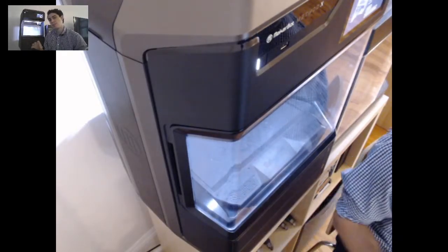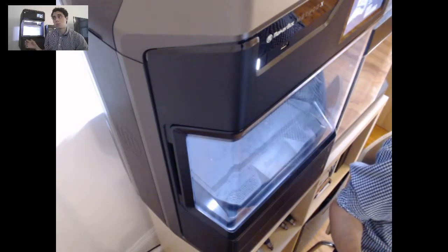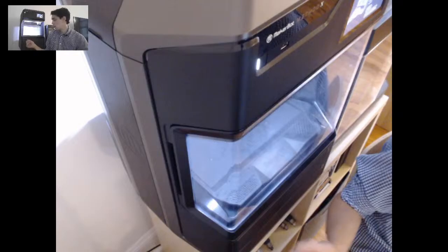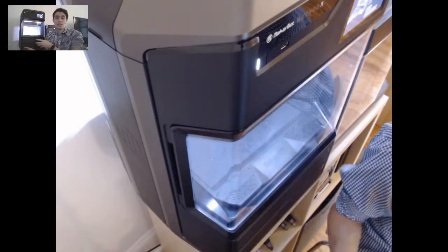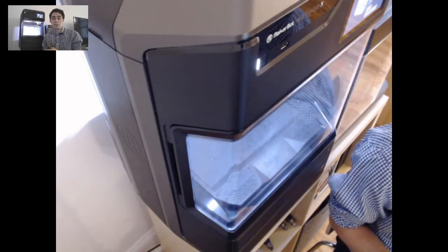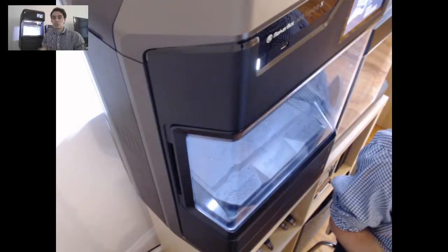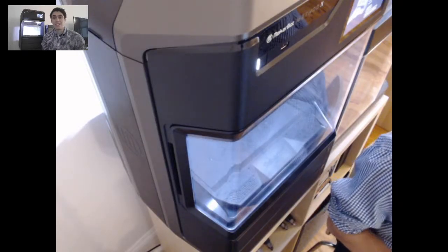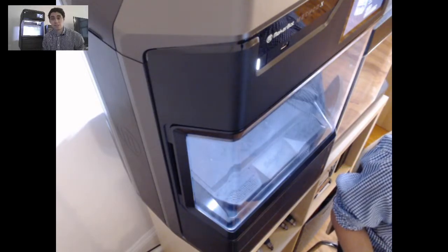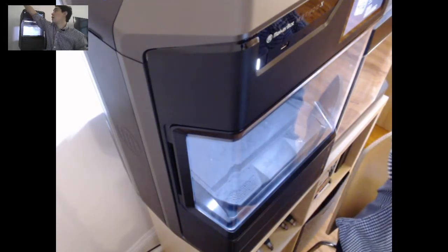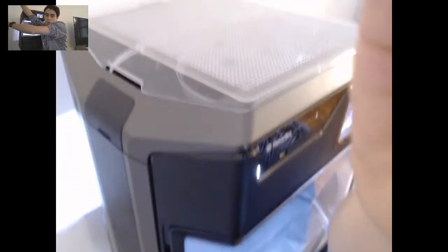This is ABS. ABS is not that sensitive to humidity. If you're storing your material for, let's say, a weekend, maybe even a week, it's okay to store it in the drawer. If it's going to be longer than that, I would say take your material out and put it in a Mylar bag or a properly dry space, because humidity definitely can damage your material. I know that I've said that a lot, but it's true, and it's impressive how much of a difference it can make sometimes.